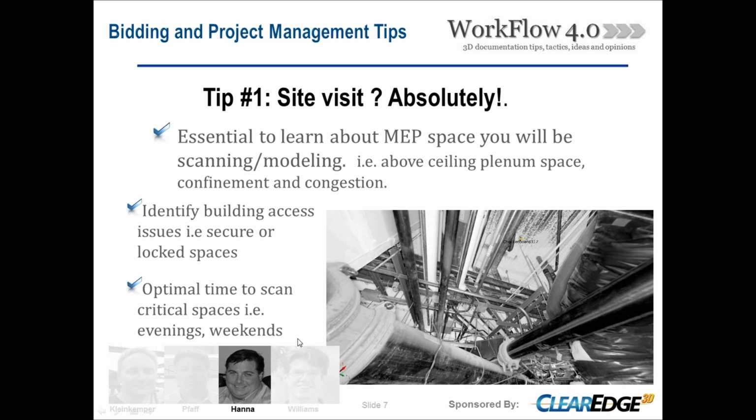Other important areas would be to understand the area you're trying to get to. Do you have access to those maybe secure spaces in the building? We do a lot of hospitals, and naturally, some areas they don't want scanners running around in there during operational time. So we have to work with the staff and the facilities department to determine times to get into those critical spaces. So oftentimes our crews are working at night or weekends. So might seem obvious, but very important.